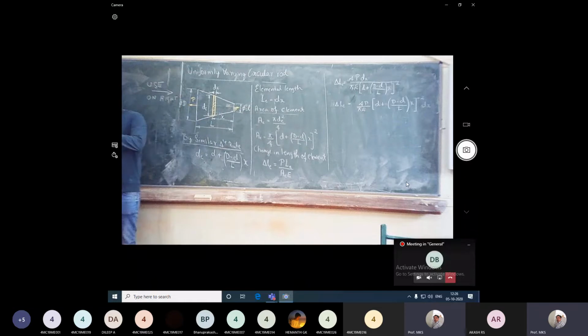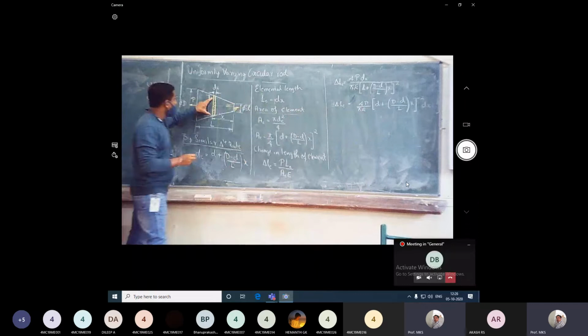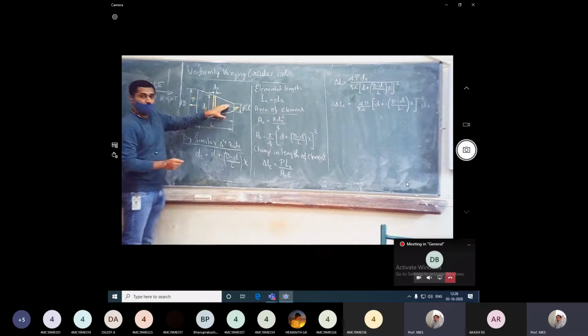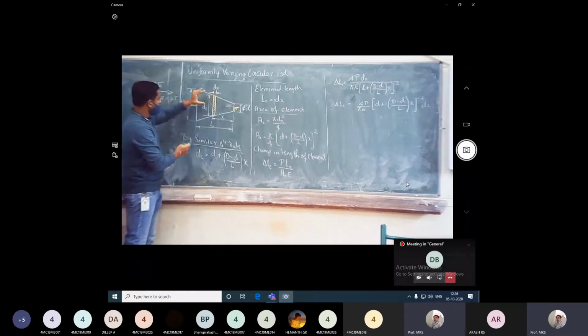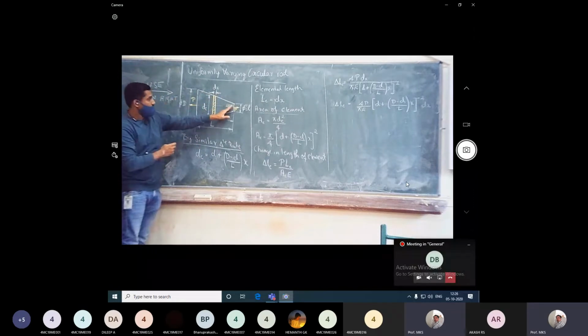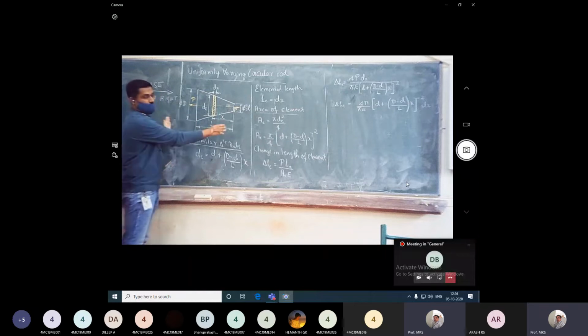So that is the expression for change in length for the element we have considered. I want the expression for change in length for the entire length of the rod, from diameter small d to diameter capital D. To get this, I need to integrate the equation for the elemental length from 0 to L, to get the change in length throughout the length of the rod.